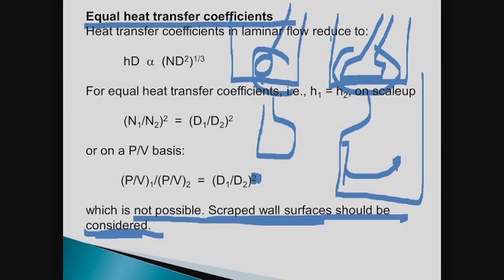So you walk away. Okay, that's a mistake, because eventually the pudding is cooking, and then the starch molecules are going to swell up, and the viscosity goes from 1 to 1,000 to 10,000. And now you're no longer in the turbulent regime. You are now in the laminar regime. Turbulent to laminar transition.